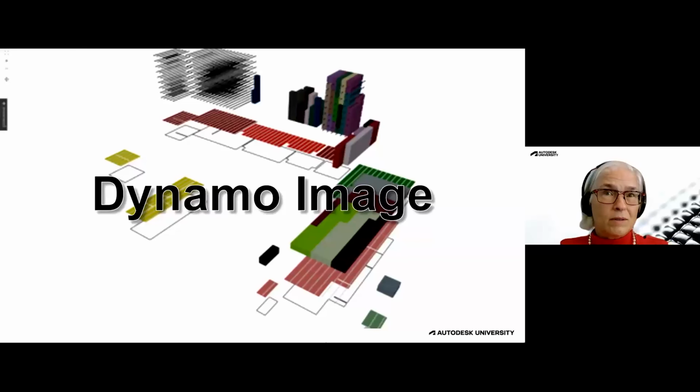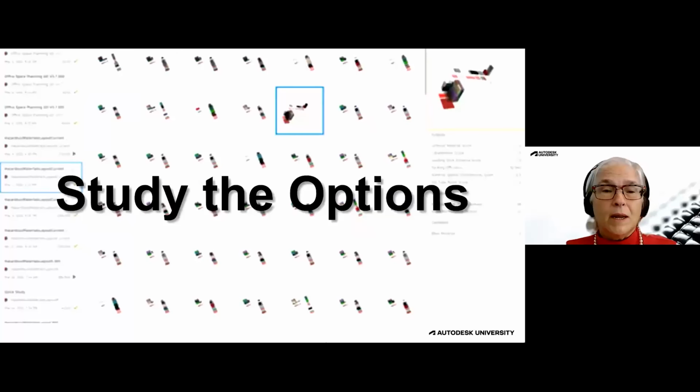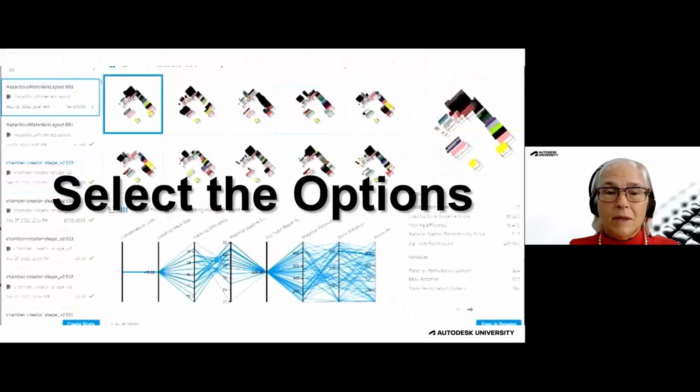Dynamo worked. The good news is the graph does perform and does organize our swidgets. The bad news is that at this point, where this image was taken, it was ignoring the existing building heights. So the software does perform, the graph does work, and we are getting options. With the correct permutation, we got as many different options as we wanted, and from the selection options in the customized graph we were able to then refine what was the best organization out of our option set.